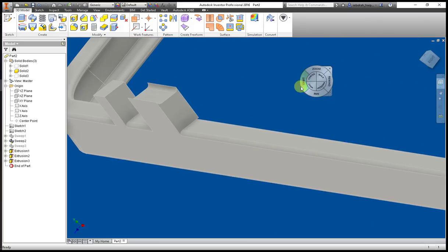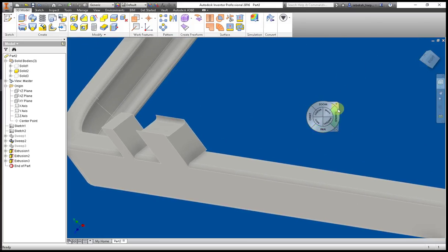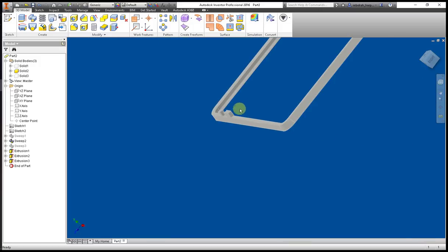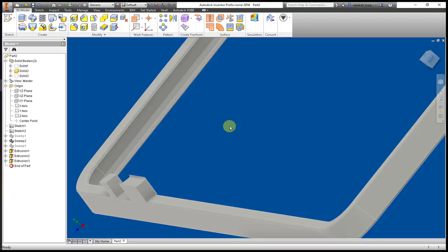So the top one you print as is, and this one already has a surface, so there won't be any or very little support material used in between, and it's a lot better that way. Make it in as many parts as you need to minimise the amount of support material, and you'll get really good results. And the bottom one the same.